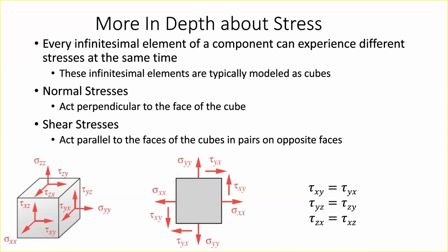You have a matrix that's 3 by 3, or rather a tensor, and there are 6 terms that you need to fully describe the loading on the part there. The thing that you do want to fundamentally understand is this. How many of you are familiar with linear algebra bases? Probably not that many. We got one. The cool thing is that you can describe the loading of a part with only 3 values, which you call the principal stresses.